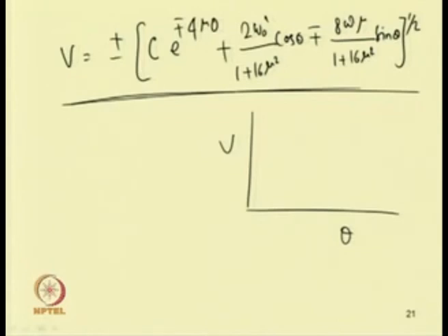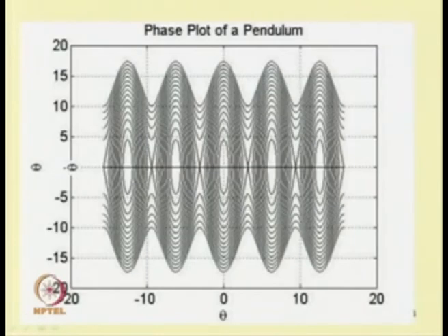If one recalls, in the case of conservative systems without considering damping, the potential well has been plotted and one can obtain stable nodes at these points. These are the stable nodes where periodic responses are obtained, and one has saddle points in between. These are the saddle nodes corresponding to the unstable points. In this case also one can obtain these two types, but the saddle nodes reduce to saddle focus.